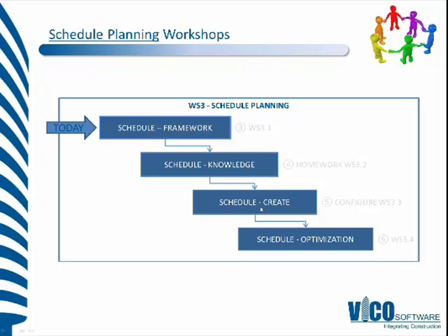When we create the schedule, we're creating it based on a defined optimum size crew, but not an optimum number of crews, and that's where the stage of schedule optimization comes in, in order to identify where the bottleneck trades are, what we can do to surround the other trades, fitting almost like a jigsaw around the bottleneck trades, and ensure that we can get a more optimum plan in the process.